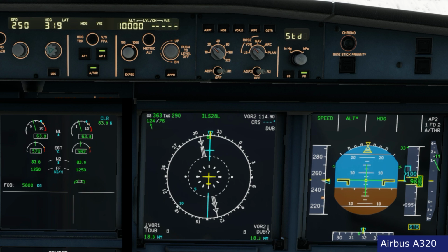Again, this usage of an open climb for such a short climb might not be the best method, because it still gives quite a strong acceleration. It is true that the Airbus has a number of logics that make the flight smoother, more comfortable for passengers, resulting in a smoother change in altitude, but still, open climb probably wasn't the best solution.